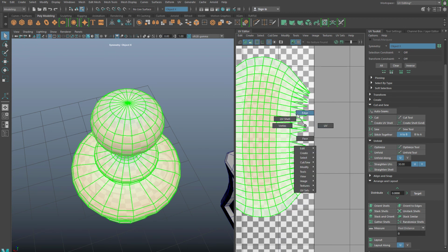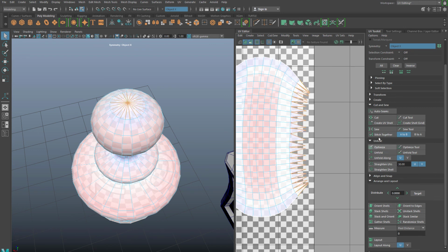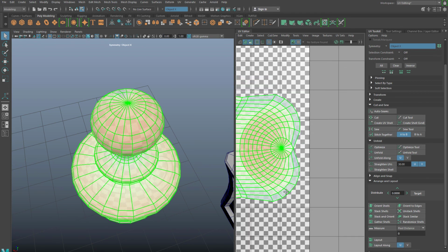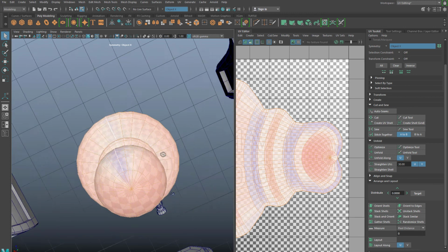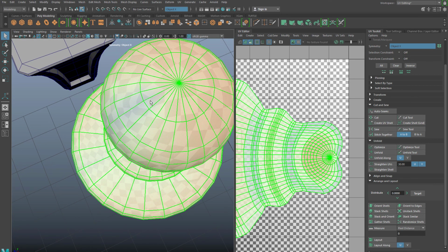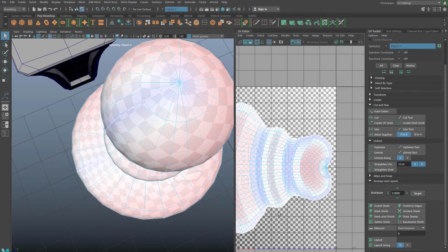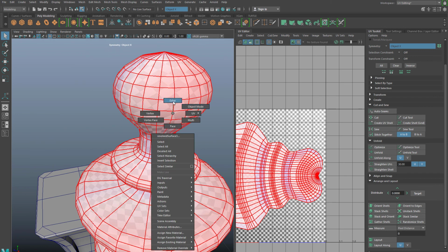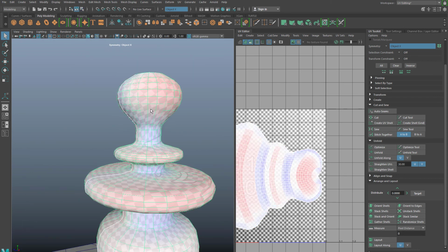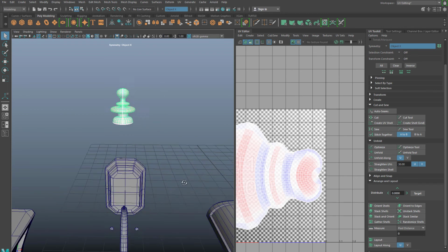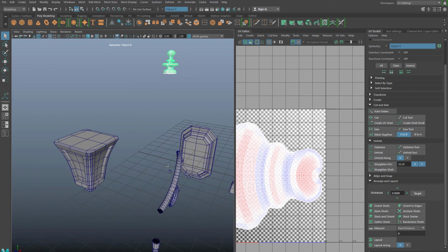Let's go to edge, select these guys, and stitch them together. And unfold one more time. And that gives me something along these lines. I do want that edge to be cut. And that'll balloon that out just a little bit. One thing that could be done if I wanted to really clean this up would be cut along something like that, so that this would lay out as a top piece, and then I could go down to the rest of it. But that'll do for what we're doing here.